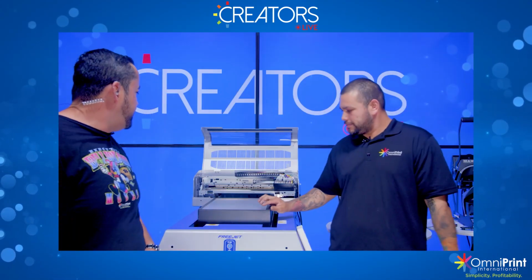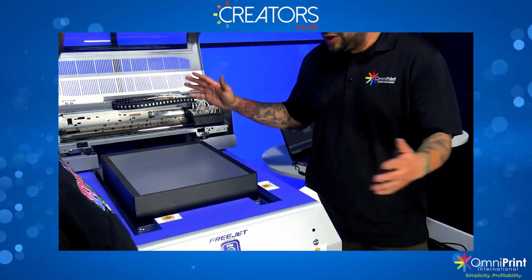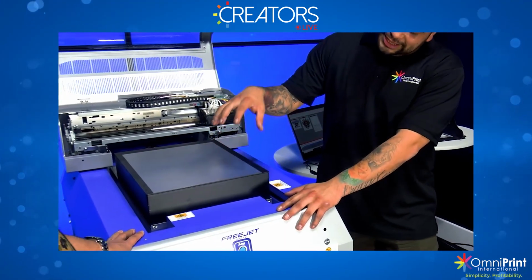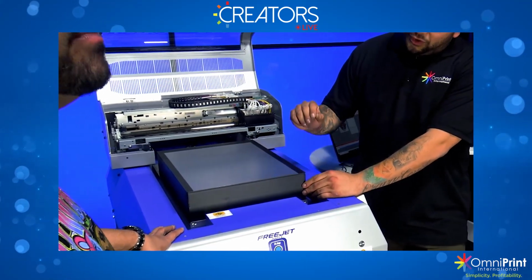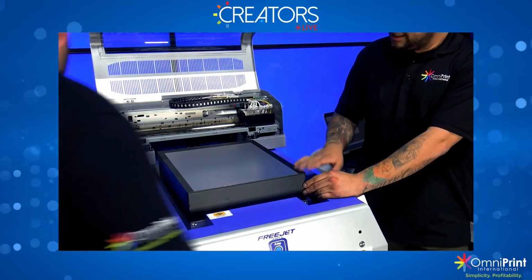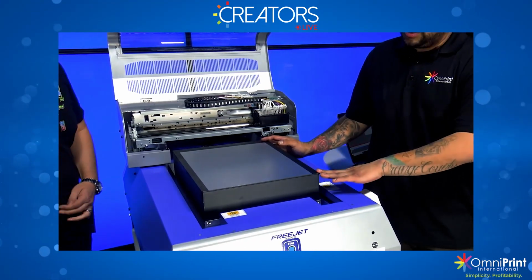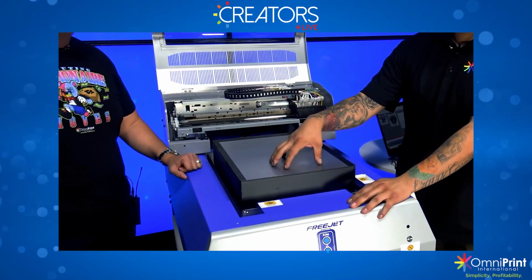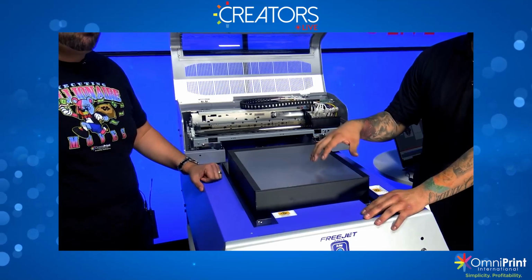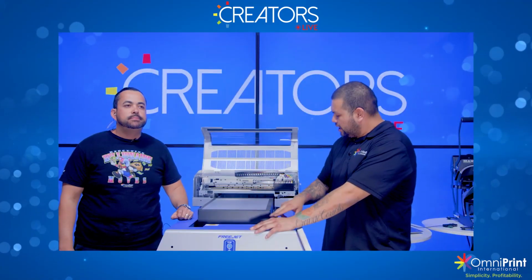What do we have on the setup right here? First, a couple of things that are new. Obviously the free jet printer, which you guys should have. And then we have this extra attachment that we created for our hot peel process. This table actually heats up. It heats up my film, which starts to heat up my ink as it prints, so I'm able to print faster and able to print on these hot peel sheets. That's the first thing we're doing.